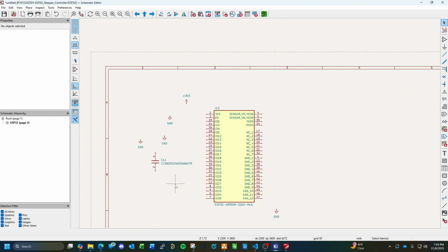Okay, that's going to be our 104 cap. Like I said, I'll dig up what resistor value I've used before in other designs. It seems to work just fine with the 104 cap. So that'll control the enable circuit. It basically delays power on for the ESP32 to give the power supply a chance to stabilize.